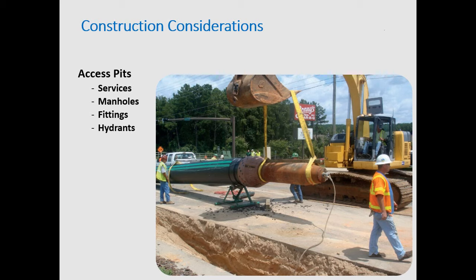And the answer is it depends on whether or not you're doing water or sewer. Sewer is relatively easy. If it's a gravity sewer, you can send a CCTV camera down, get that type of information, and you know where your service connections are, that type of thing. Water systems are more complicated because it's a pressure pipe. It's more impactful to get in there and open it up and figure out what's going on. There are technologies out there, albeit somewhat more cost prohibitive depending on what level you want. So for your water lines, generally you go to your record drawings and then maintenance reports. So, good question.